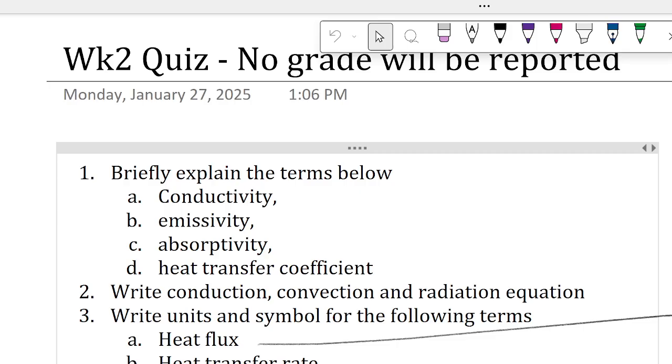Emissivity again is a property of the material. Make sense? But we are getting somewhere close to the result when we get the temperature from the radiation gun, because the emissivities of those things are very close. Okay, not always. Brighter surfaces have really lower emissivity, darker surfaces really higher emissivity. If you have a perfect black body, then you could assume the emissivity is 1 or 100%. Is it clear? Those are the things you learn slowly, okay? But this is just the overview.